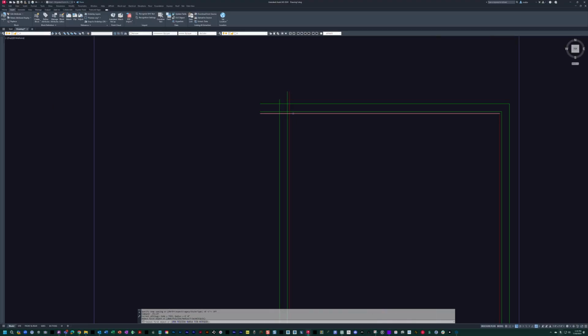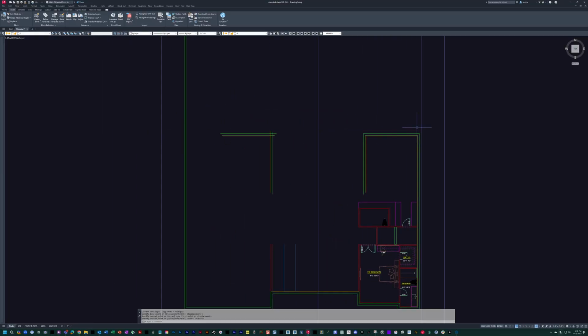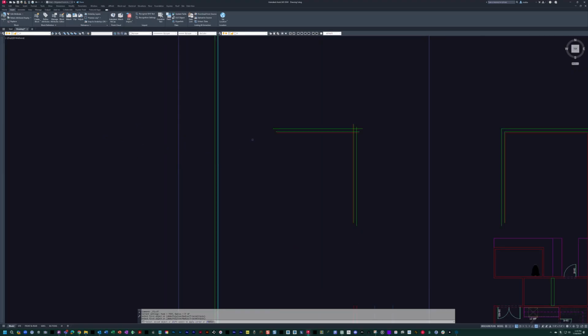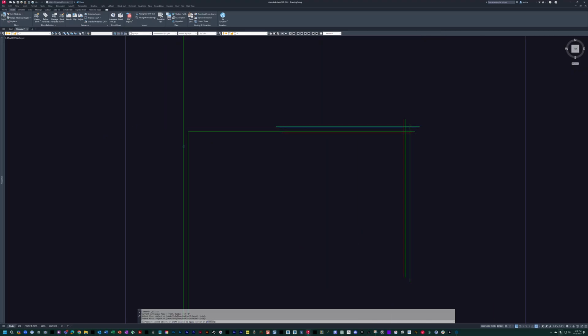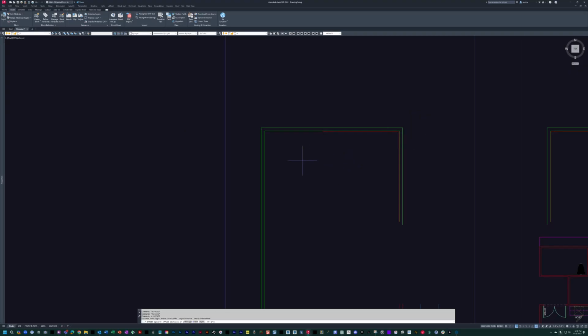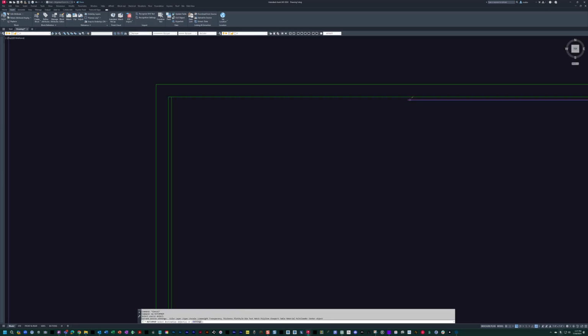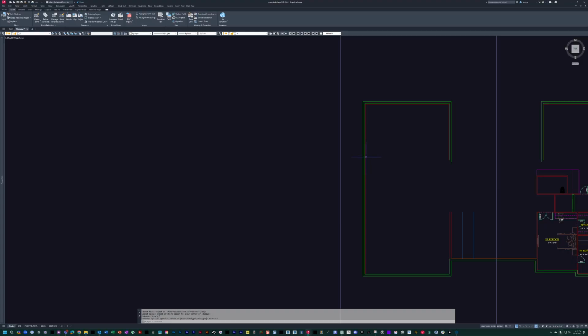Really nice. So we can fill this all up, and we know that these walls are going to be even across the back, so we just created that connection, and really getting a head start on things. We'll offset this 2 inches. This is for our furring off the block wall. Oops, let's continue filleting that. And we can just pull this up here somewhere.